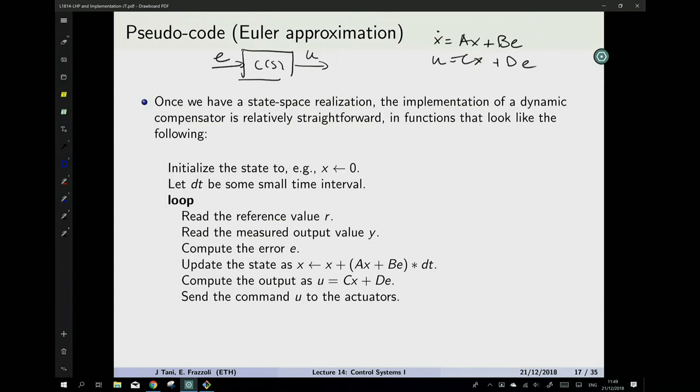Well, first of all, the whole point is, given the inputs to the system, the errors, those are inputs, so they're given, what should U be? And the controller design that you did gave you A, B, C, and D, which are now known. So first thing you write is, this is an ordinary differential equation, right? You know from other classes that ordinary differential equations need initial conditions, otherwise you can't even start talking about things, right?